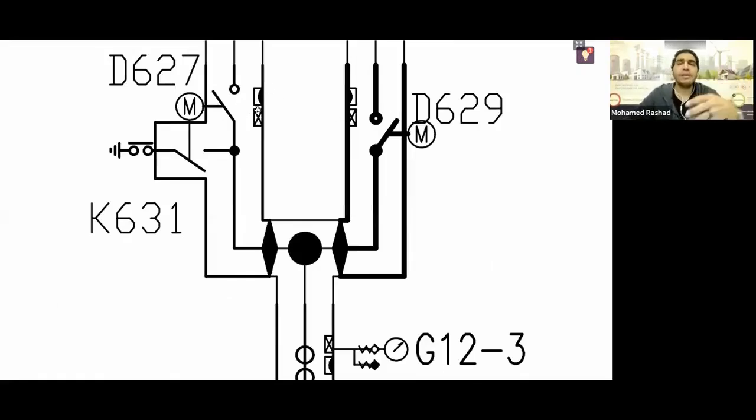First, the absorbent zero, which is considered silica gel, and it is indeed silica gel. You find a piece sticking out a bit like a cap covering it. This contains silica gel inside to absorb any moisture that might be present inside the SF6 gas. Why? Because as I told you yesterday, SF6 gas decomposes at the moment of a short circuit.